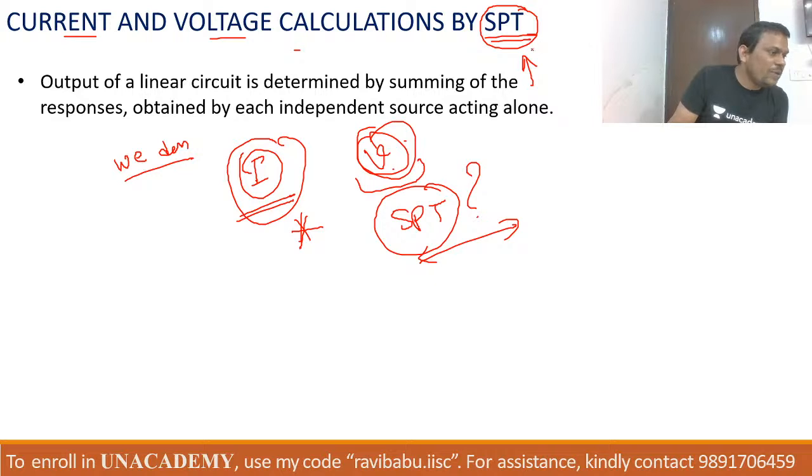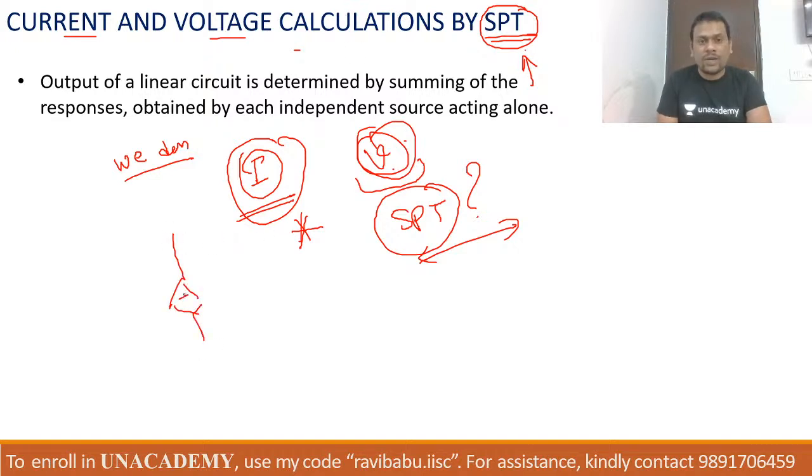Yeah, what is the doubt, beta? Yeah, Karimullah, so the doubt is, okay sir, if the dependent sources depend on short circuit sources, what happens? Yeah beta, in that case you can make short or open. For example, I want to say, beta, suppose one dependent source is given in the circuit, and let us assume something like this is our circuit.